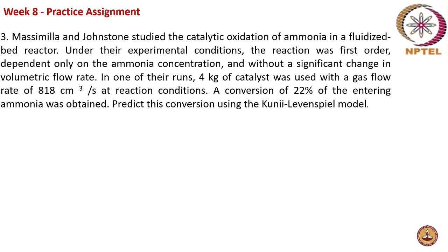Okay. So, in this particular question, this ammonia oxidation has been carried out in a fluidized bed reactor with a catalyst quantity of 4 kg and a gas flow rate of 818 cm³ per second, and they have obtained a conversion of 22%. This is the observed conversion rate. Now, they have asked us to predict this conversion using the Kunii-Levenspiel model.